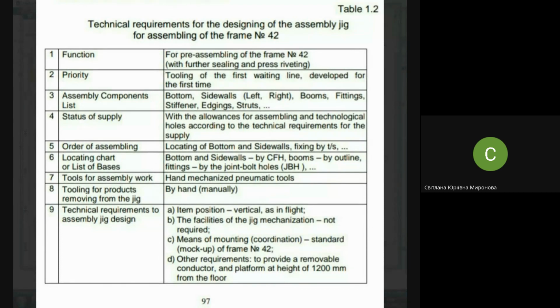You write the technological process, and you pass this technological process to the next engineer, whose responsibility is to design tooling. But this other engineer, who works in the department of auxiliary manufacturing, should not spend dozens of hours to understand how it's assembled, what are your ideas, and so on. And together with the text of technological process, together with previous documents which were origins for you, all those locating charts, part supply conditions, and above all the assembly diagram, of course, which shows the sequence of assembly.